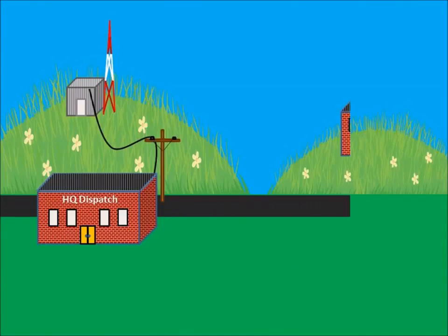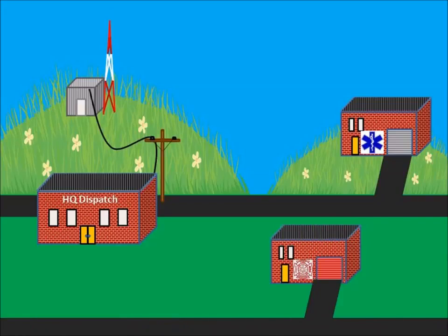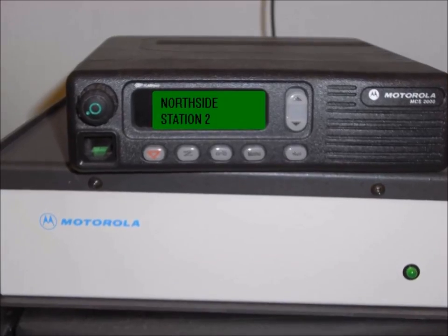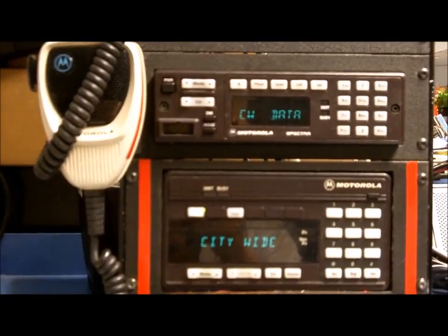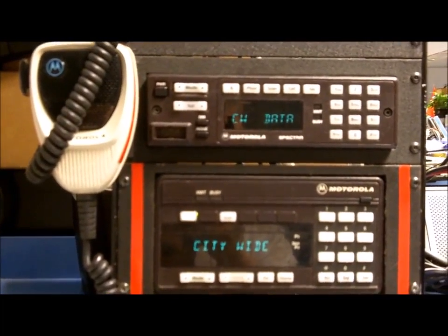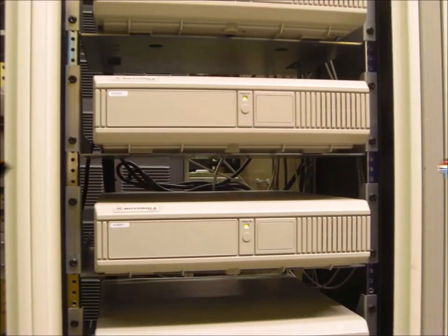If your agency has multiple locations that need to access the system, control stations would be a good choice of equipment for this purpose. These standalone stations are effectively desktop subscribers, perhaps a mobile radio using a 12-volt DC power supply, or a station specifically designed for this purpose. They don't have supervisory capability because they're linked by radio and have no direct connection to the base stations.